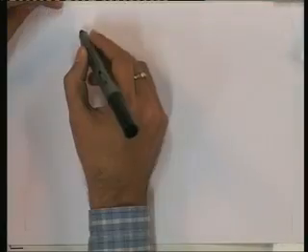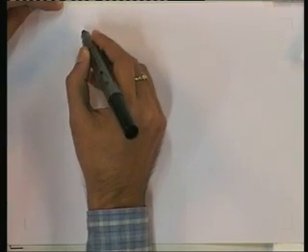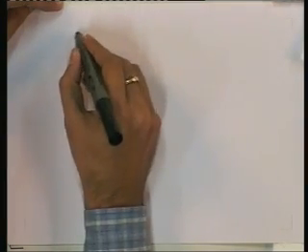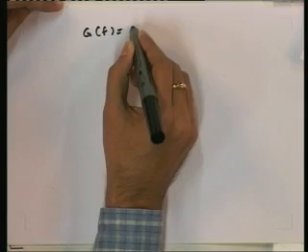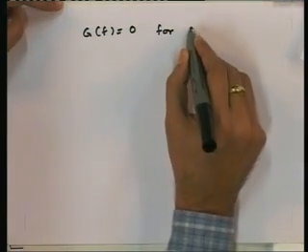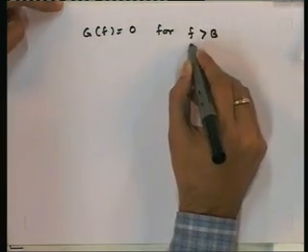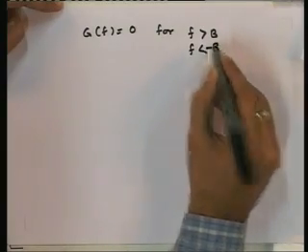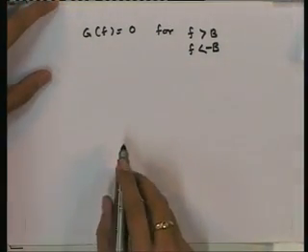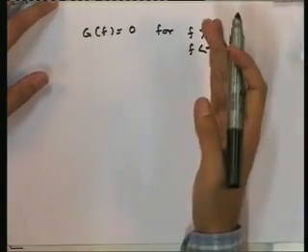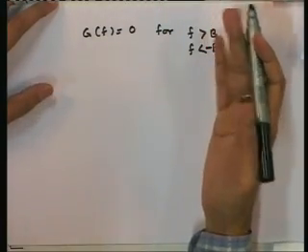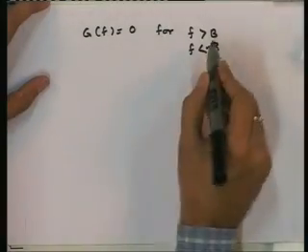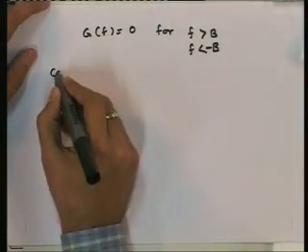So first suppose that G(f) is band limited to B, that is, band limited to frequencies from minus B to plus B. That is, G(f) is 0 for f greater than B and f less than minus B. So there is some B for which this will be satisfied, though it may also happen that B is infinity. Now case 1 is